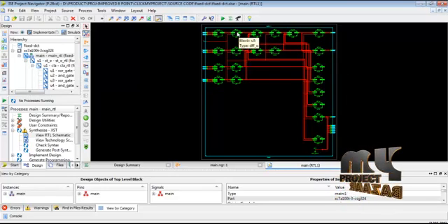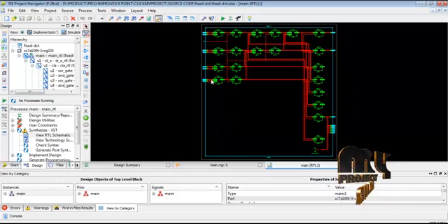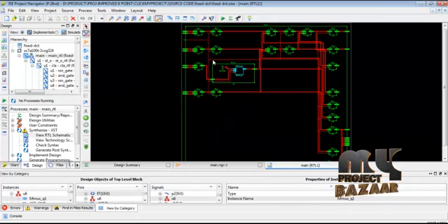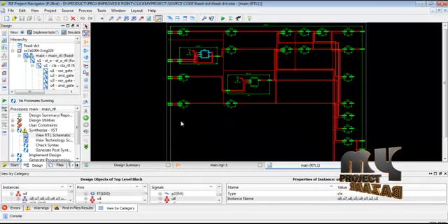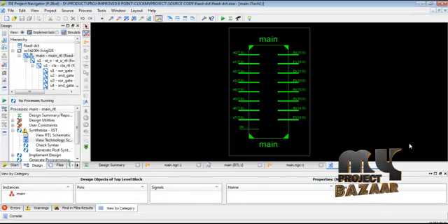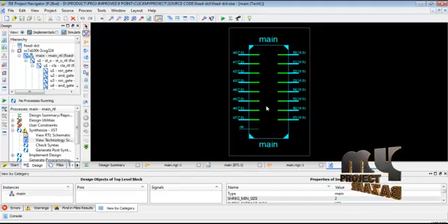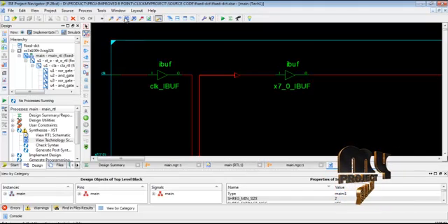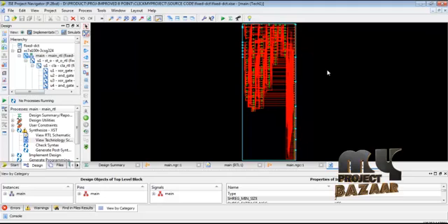The 8-point DCT architecture uses only 14 additions. Each and every module makes up the overall architecture. Then we apply the technology diagram. The RTL diagram represents the logical blocks placed in our architecture. The technology diagram represents the lookup tables, bounded input outputs, and the flip-flop pairs placed in our DCT architecture.